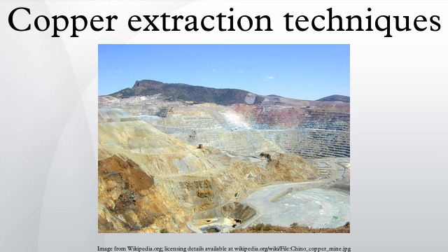The term matte grade is normally used to refer to the copper content of the matte. The purpose of the matte smelting stage is to eliminate as much of the unwanted iron, sulfur and gangue minerals as possible, while minimizing the loss of copper. This is achieved by reacting iron sulfides with oxygen to produce iron oxides and sulfur dioxide. Copper sulfide and iron oxide can mix, but when sufficient silica is added, a separate slag layer is formed.